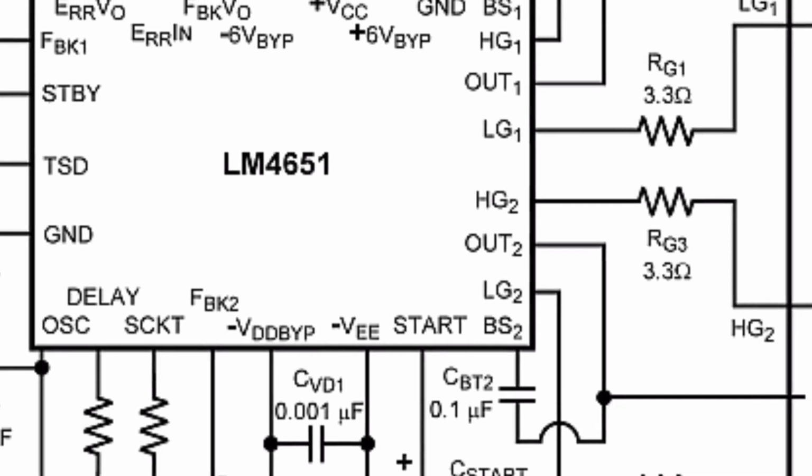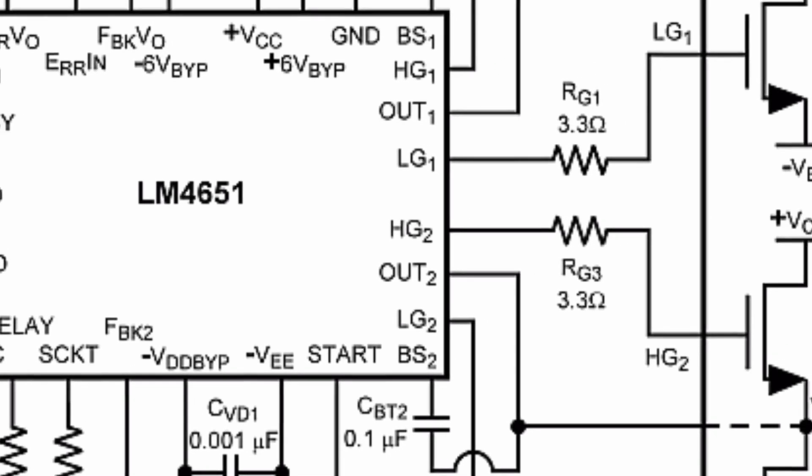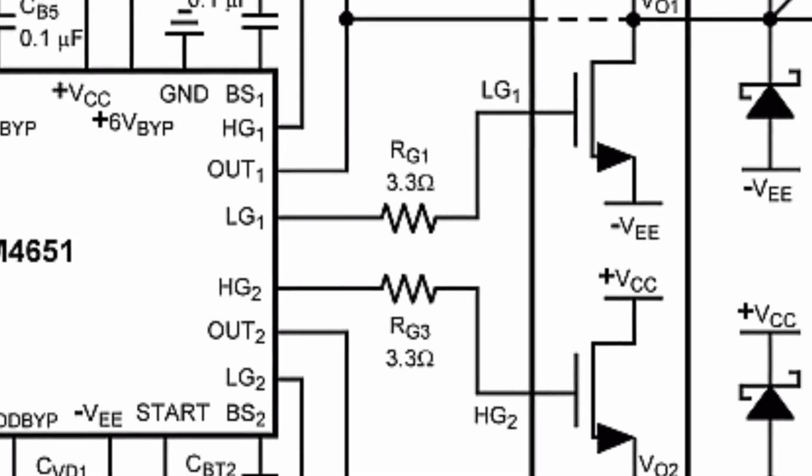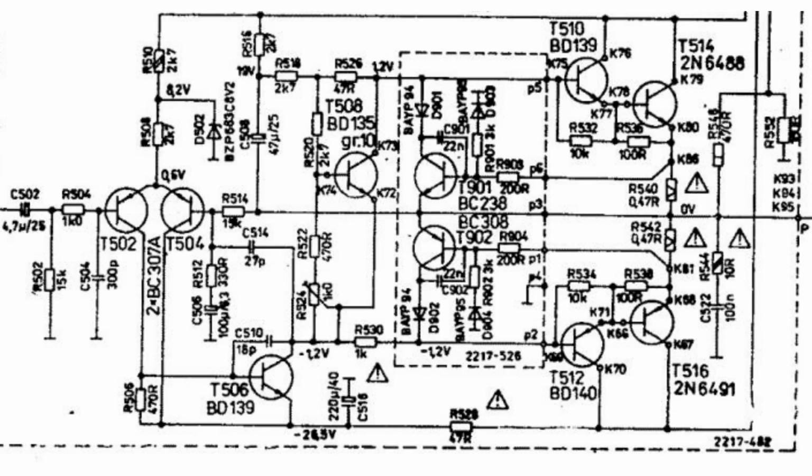Class A, B and C are the three common classes, but you can have variations of them. Before the era of high-speed switching transistors like MOSFETs, there was a need for high power amplifiers that have small distortions. Engineers figured out that by adding features from Class A and Class B, you can have an amplifier that has a small distortion like Class A and high efficiency like Class B, and higher power output. And this is how the Class AB push-pull amplifier was born.